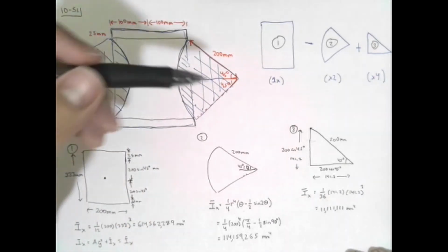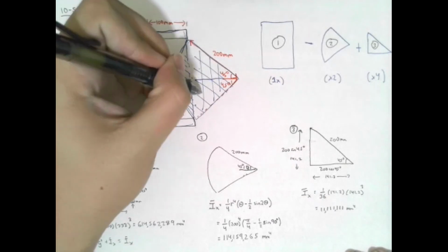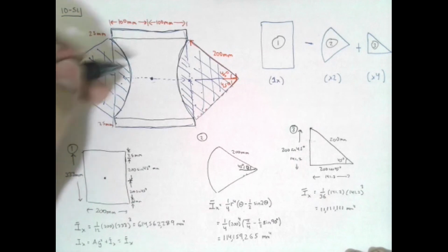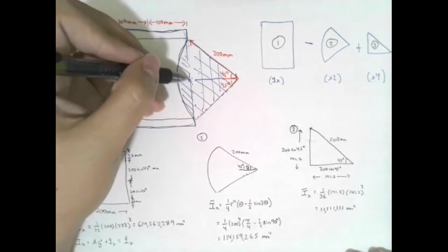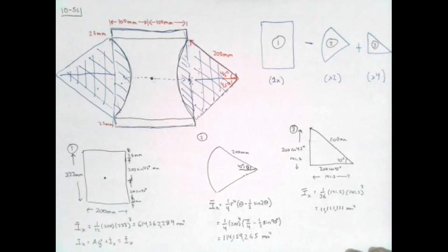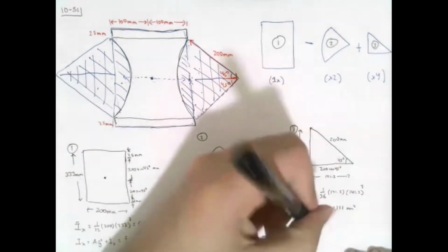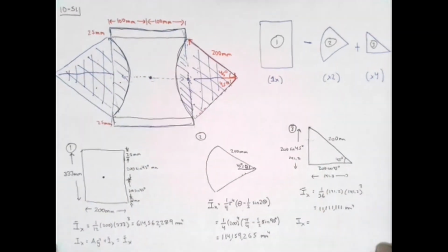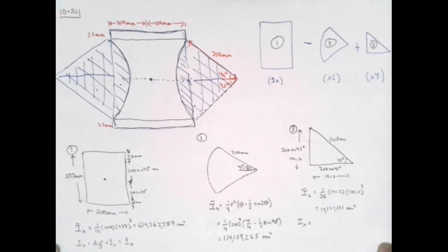Now, the good thing is that the centroidal axis for these four triangles is at an equal distance from the centroid here, right? Because they're all going to be at 1/3 of this distance, which is all the same. But we still need to apply a correction, to find the moment of inertia about the x-axis for this triangle.